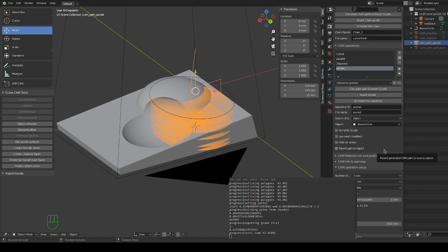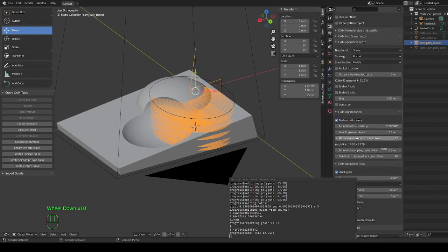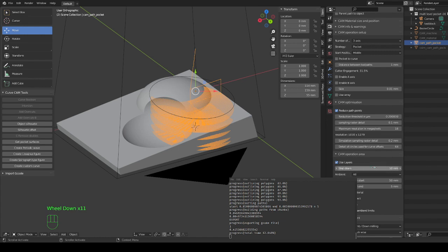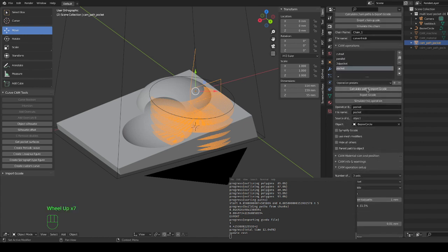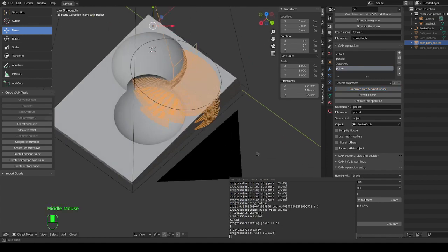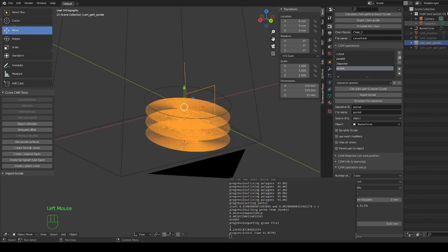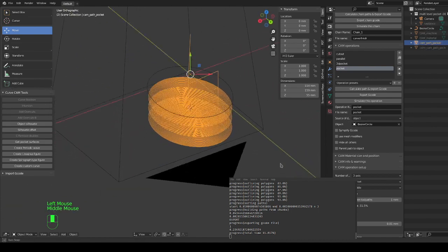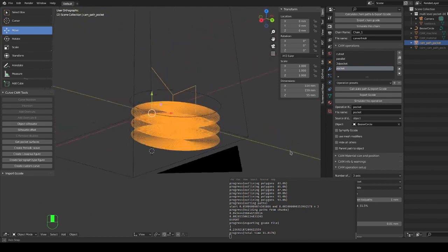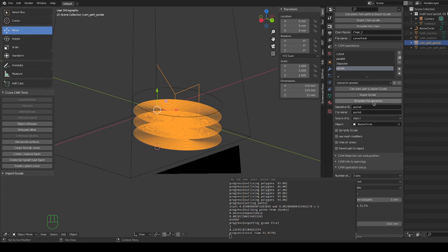Okay, so my options were to calculate at a certain depth in layers, step down of 10 millimeter. So if we use a step down of 15 millimeter, let's say your material and cutter can handle that, I'm going to calculate it again. It's relatively fast and painless. And so it's going to drill a hole, and right now I have an object in the way, so let's make it disappear because it's not really important right now. So the test block is here, and it's going to just make a pocket really deep, and so we can simulate this.